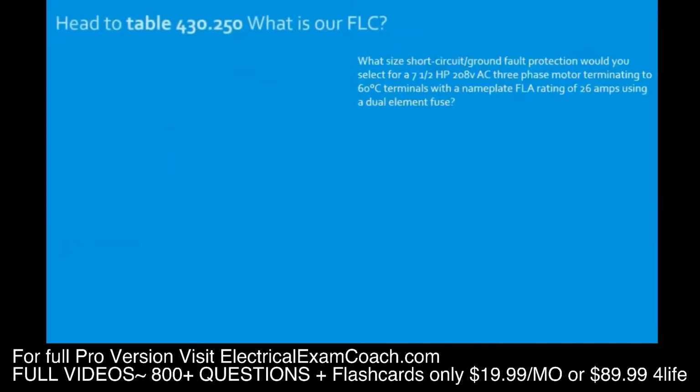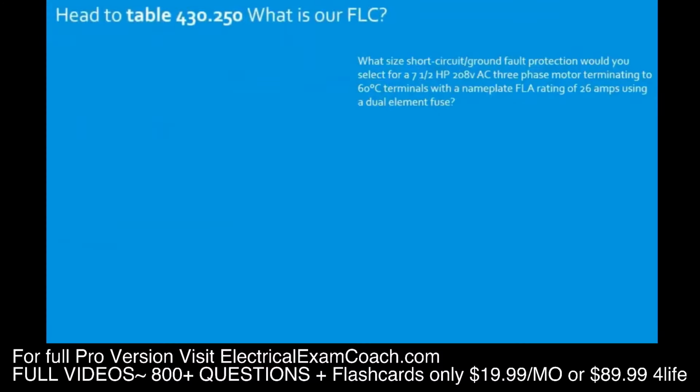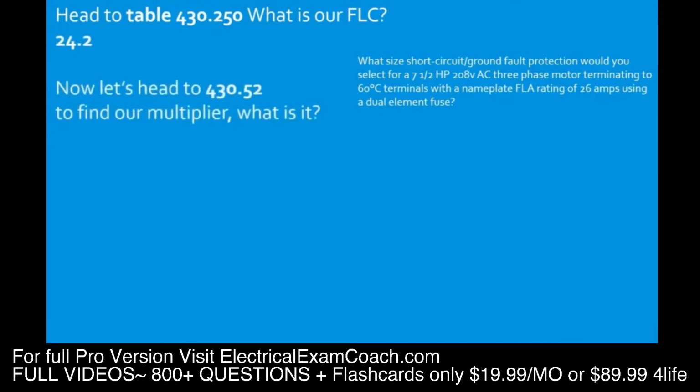Now we head to table 430.250. What is our FLC? Starting on the left with horsepower, coming over to the voltage, we find that our FLC is 24.2 amps. Now we head to table 430.52 and find our multiplier.